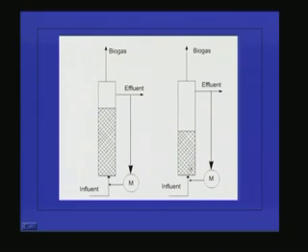And now coming to the expanded bed reactor, this is an example of an expanded bed reactor. Here all the particles will not be in the expanded form, all the particles will not be in the fluidized form. Here the upward velocity will be relatively low compared to the fluidized system. So the bed will expand up to 30% of the initial height. Say the initial height was only up to here, after the influent passage it will expand up to here. So how can we distinguish the fluidized reactor and an expanded bed reactor?